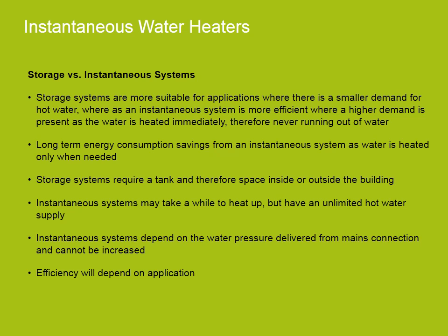One drawback of instantaneous heaters is that they depend on the water pressure delivered from the mains connection, and it cannot be increased. Therefore, if the original pressure is low, the hot water will be supplied at the same pressure. One system is not necessarily superior to the other. It is more a matter of matching your client's needs to an appropriate system.